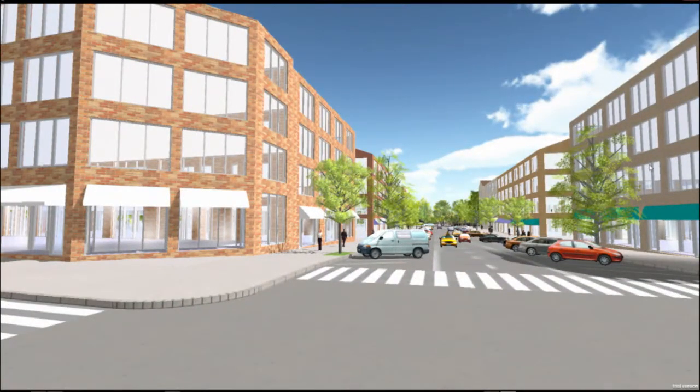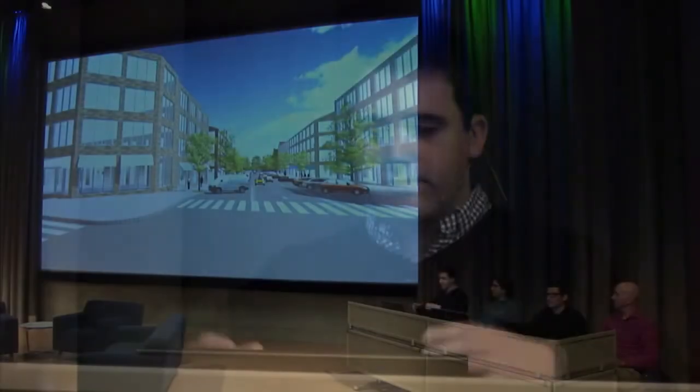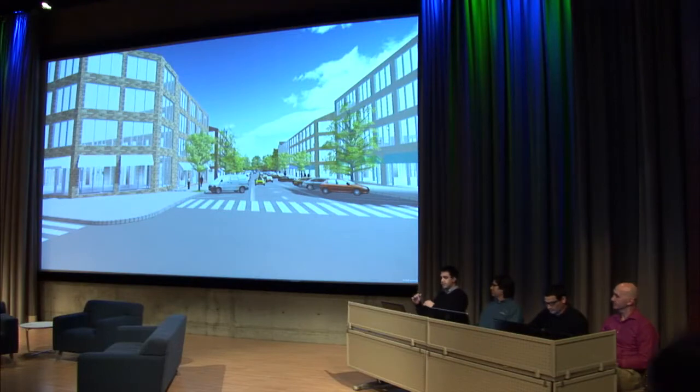Yeah, quick question for you, Brooks. Yeah, sure. Is there a vision for actually building reporting into these kind of vegetation objects so we can track cost, track water consumption, et cetera? Right. Similar to the buildings that outputted those reports, we can pretty much report anything in CityEngine. The area, the object, different volumes, different lengths. So those trees have their heights. There's a height range, a minimum, maximum grow out that's represented by those analytical models. And with that, you can start to count the trees, start to estimate costs, exactly.